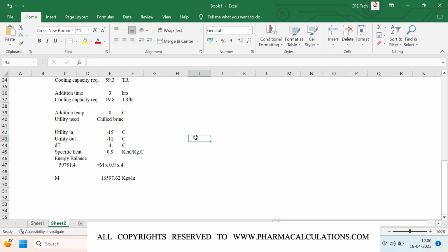So coming to the densities of the chilled utilities. I have a list here. If it's chilled water, the density is going to be approx 960 kg per meter cube. And if it's a chilled brine, which is at minus 15 degrees centigrade, the density is going to be almost 920 kg per meter cube. Why? Because we are going to mix methanol with the chilled water so that you can attain this minus 15 degrees centigrade without freezing, and the composition you can back calculate using this density.